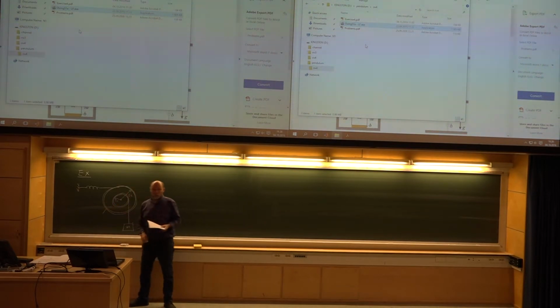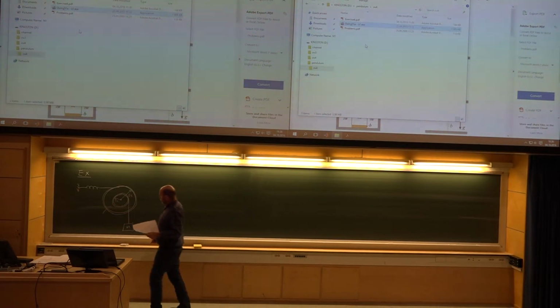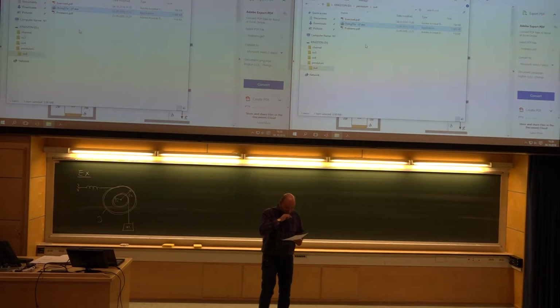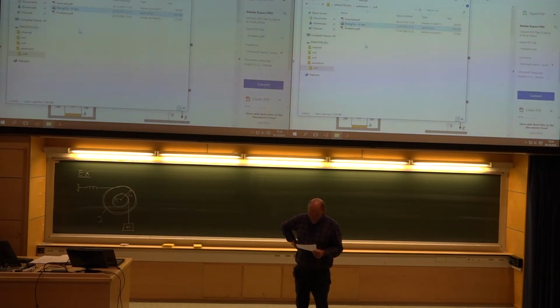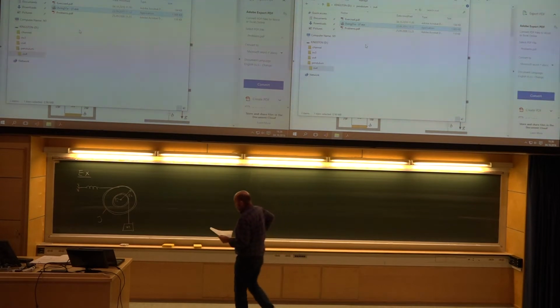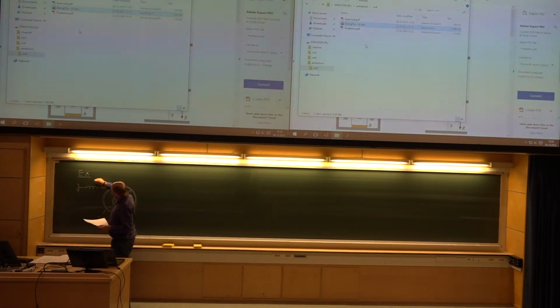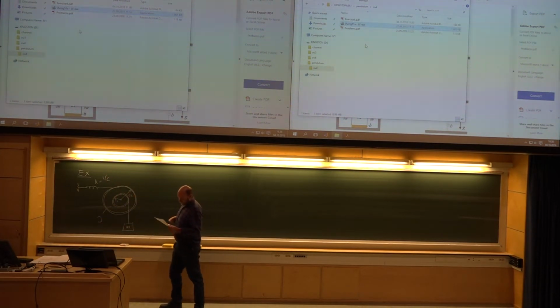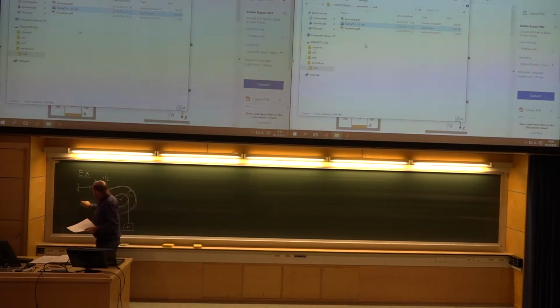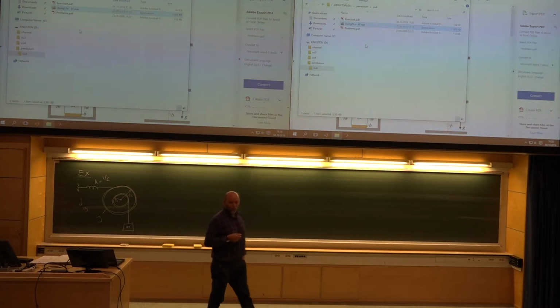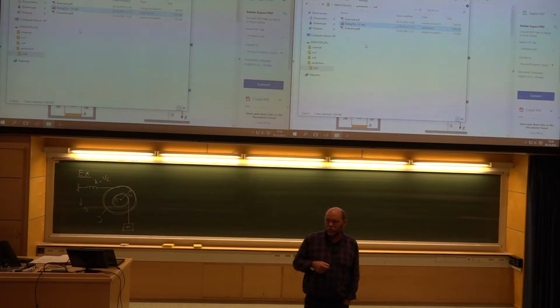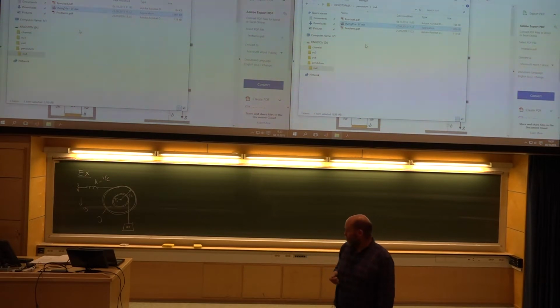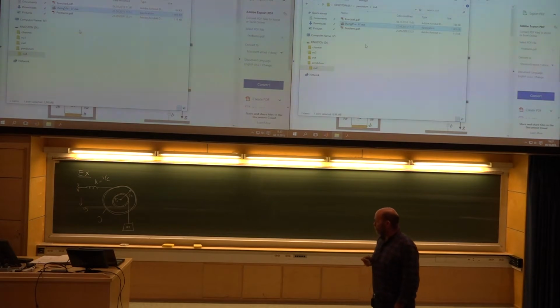This wheel also has inertance. I call that one J, rotational inertance. The spring stiffness, yes, we have a K up here, which then is of course 1 over C. We have the radiuses, then I think we have everything, and also of course the system is attacked by gravity. Find the bond graph, find the differential equations, find the state equations necessary to describe this system.